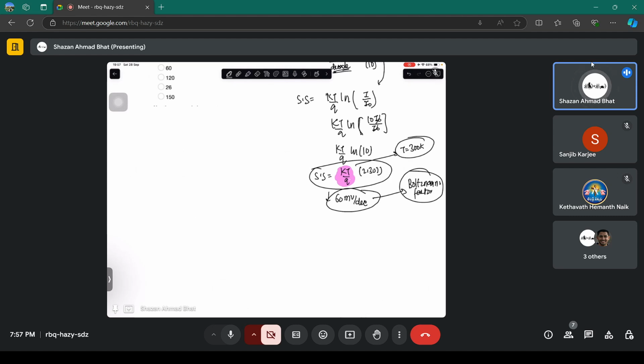If you reduce the temperature, you will get a lower subthreshold swing. What determines how fast you can change the current with respect to the gate voltage is temperature. That means nature, the Boltzmann distribution. If you play with those distributions, you are going to reduce the subthreshold swing.